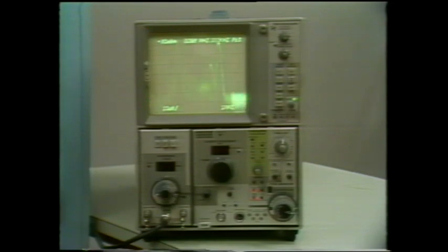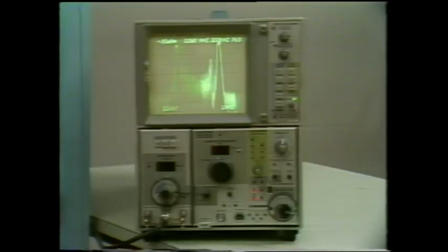This is an off-air television signal. Before we actually make the noise measurement, there are a few things that you ought to remember. First, you may have to amplify the signal so that you can measure the noise. The video signal is a pulse signal, so a fairly wide resolution bandwidth like 300 kilohertz is very appropriate. And don't forget to normalize to the television bandwidth from the analyzer's noise bandwidth and compensate for the instrument characteristics after you've made the measurement.